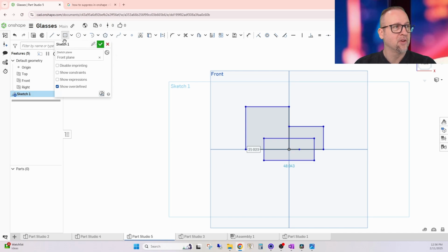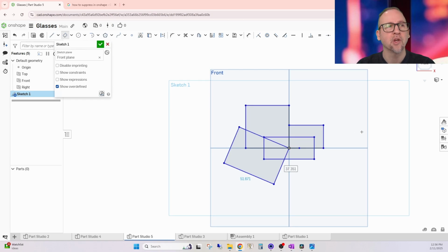All right, the third one is an aligned rectangle. Let's say we click here, and then we can create an aligned rectangle. So those are the different types of rectangles that we can do. If we want to start creating some sizes on these rectangles, we can go over to the dimension tool here, or click the key D. Okay, let's do this right here, and now we can choose sizes of this.